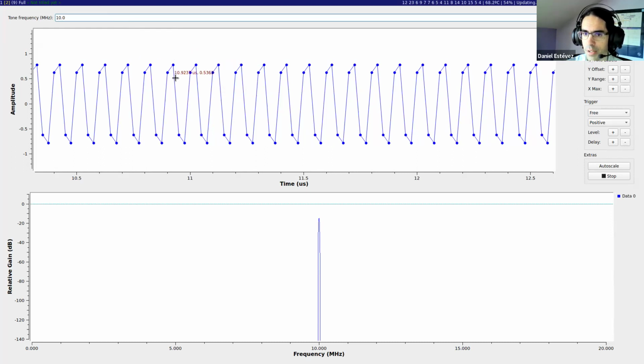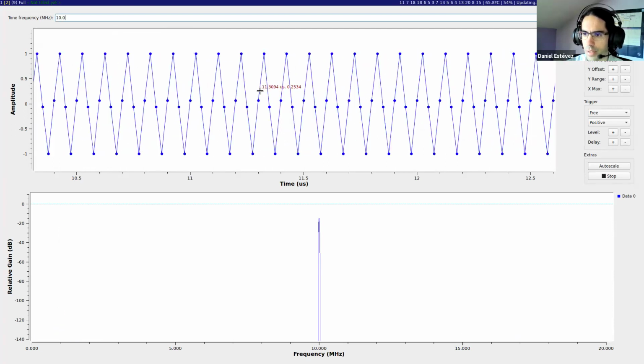So we can change the frequency, but the phase will continue in its current value. What has happened here is we are still looking at a 10 megahertz cosine, but the phase is different from before. So rather than having the first sample where it is +1, we have it somewhere else. But you can still imagine the cosine. It would go like so and like so. Just to demonstrate, again, I'm going to say 1 megahertz, 10 megahertz, and now we get a completely different phase. It looks similar to the first one, but it's not exactly the same because these are not exactly at 0.